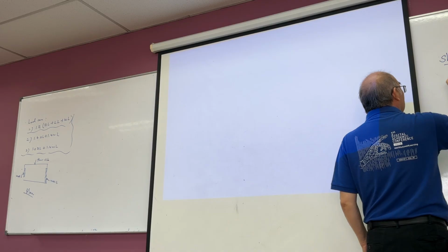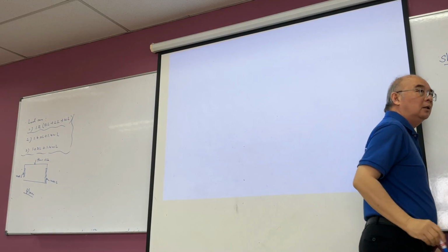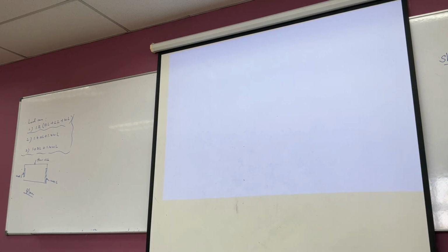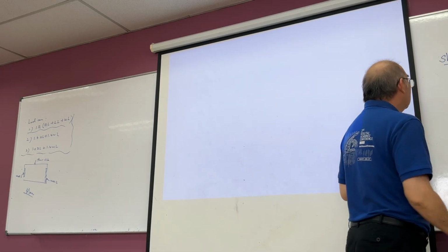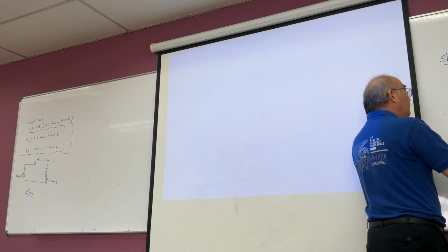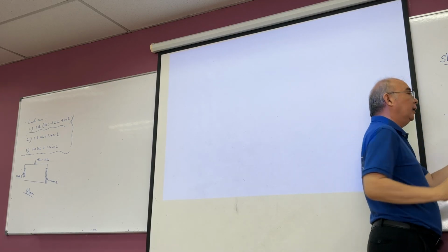First is to get the PU and the MU. Okay. So the shear wall, let's say this is the shear wall. Okay, I need to get the PU at the base, and then the MU at the base. Okay? From here you do the PU over BH, which is the axial stress.